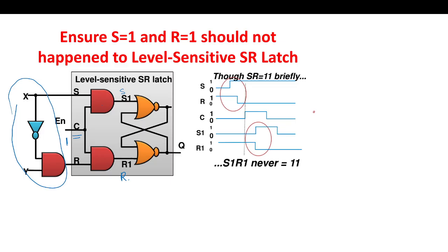Verilog code for RAM. Okay, so it is like memory, and for memory, say we use register. I want a memory which is of 8-bit width, so 0 down to 7, and I want say some 256 memory locations, so 255 down to 0, something like this. Then you can have an address bus, address again of register type.